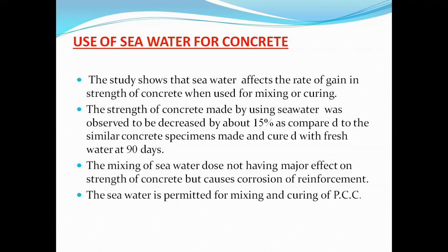But for economical purposes or other reasons, if seawater cannot be avoided or there is a single option to use seawater, then we have to use it with certain guidelines, and we have to make the concrete more dense so that we avoid the corrosion of the steel reinforcement. So that is about the use of seawater.